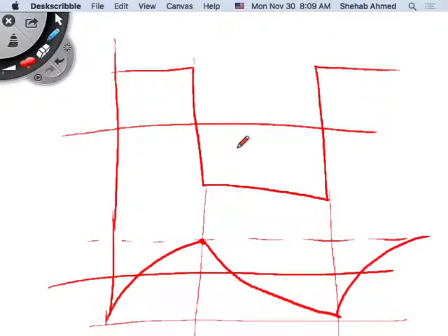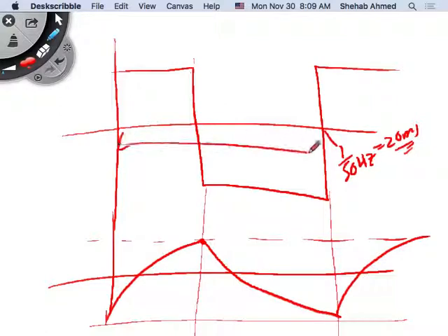So that's the final objective here. So this is nice and simple, a nice and simple waveform. You are switching at your fundamental period. So if this is 50 hertz, which is 20 milliseconds, this is your switching period T. Here you have devices 1 and 3 on, and then here you have devices 2 and 4 on, for example, for the full bridge. You're making the switching once every period. So the switching frequency is 50 hertz.